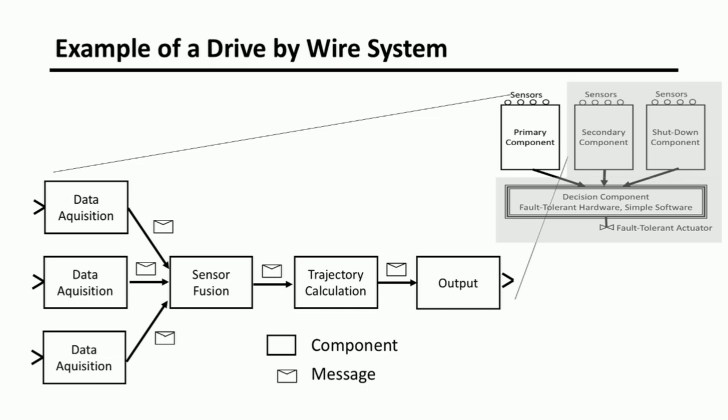So this again is a very powerful application of the principle divide and conquer. And this is, I think, one of the reasons why time-triggered architectures are so much better than event-triggered architectures, where the temporal and the value domain is always intermixed, and you always have a change in one and the other and so on, and you never can get this clear separation of concerns.